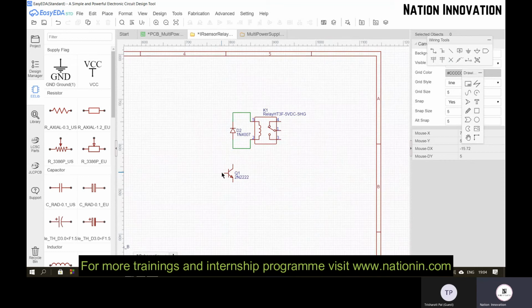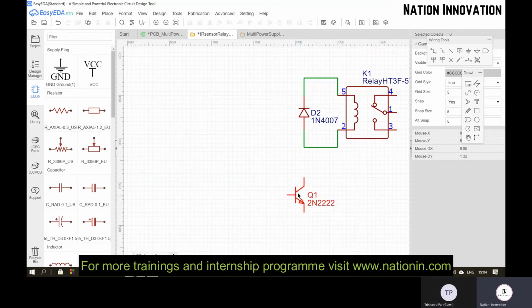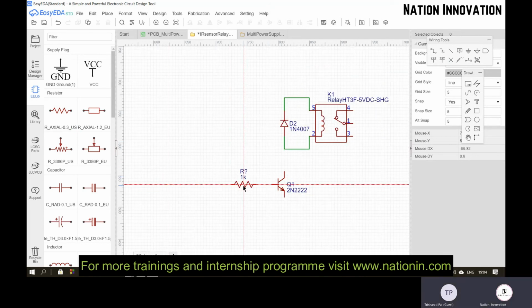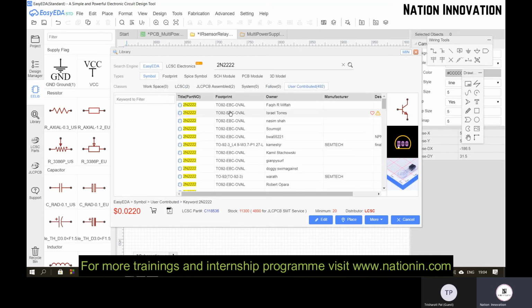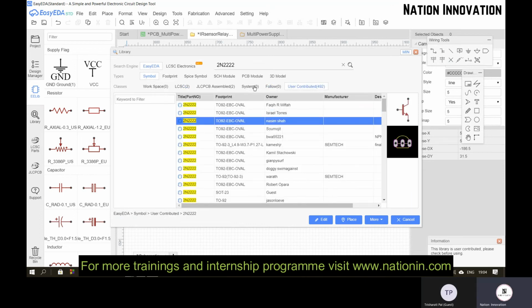Ma'am, this one is not an SMT component. No, all are through hole only. How do we understand whether this is through hole or SMD? In the case of your footprint, if it has a hole, then it is a through hole component, or if it has a red color pad. Let me show you. Ma'am, is this one SMD or through hole?